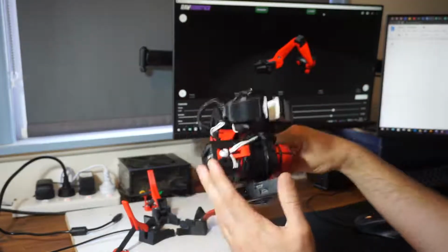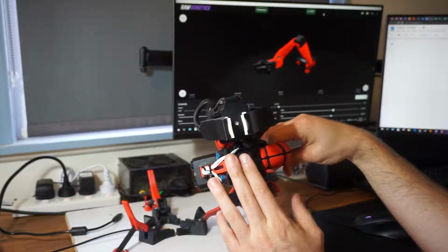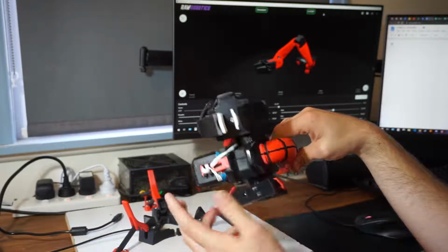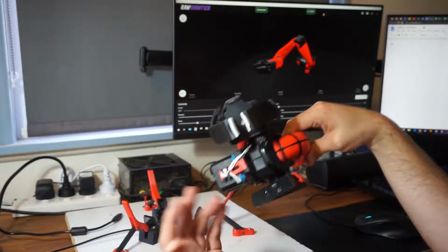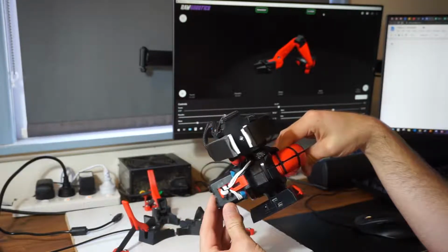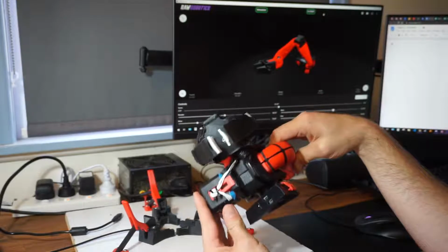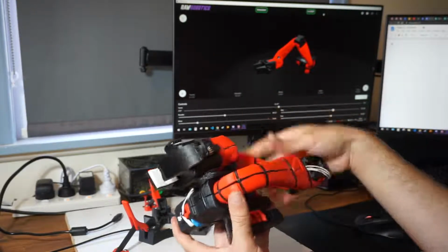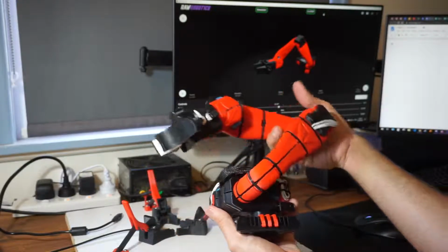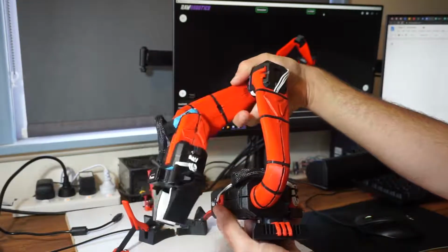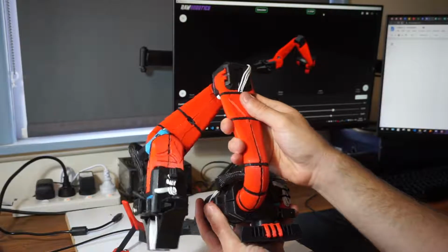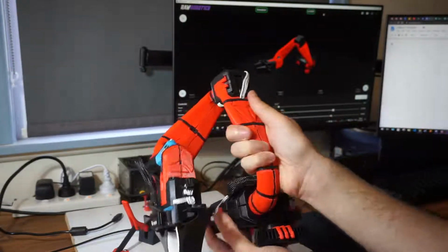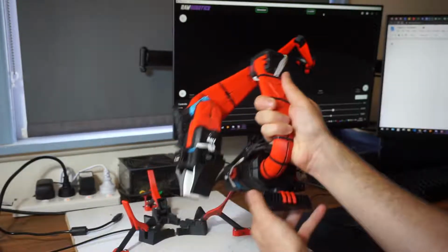because the shoulder motor actually goes through a 2.83 to 1 gearbox, which means that for every revolution of the arm, the shoulder motor is rotating multiple times, about 2.8 times. So its absolute position encoder doesn't know where in that rotation it is unless we move it to a roughly known position. So that position is about 90 degrees. It just needs to be somewhere between 0 and 120, preferably well between them. So 90 degrees is a good reference point and it's easy to remember.